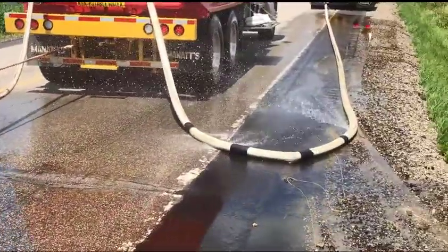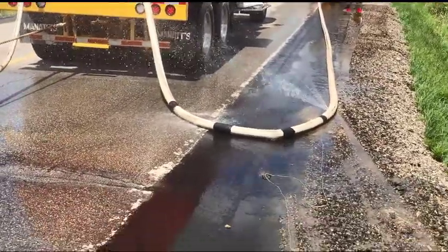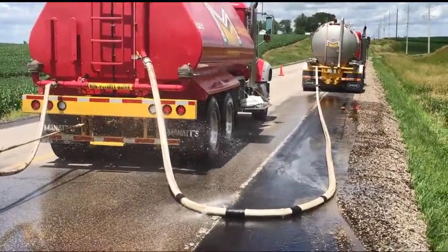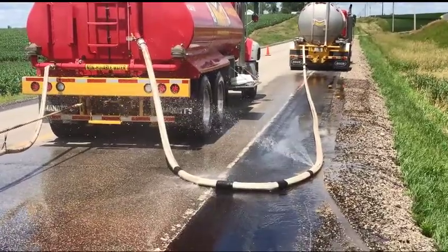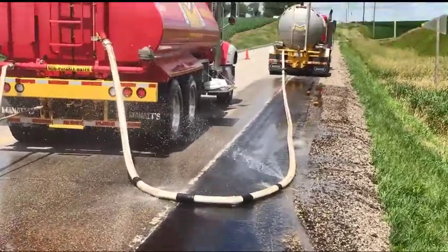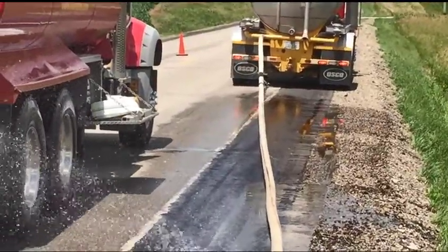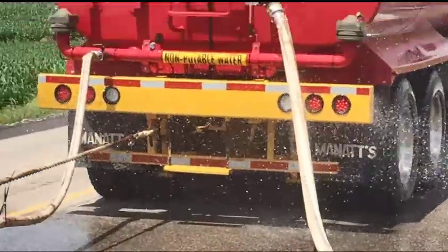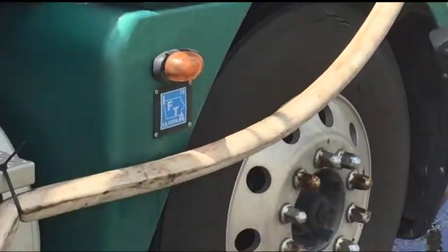But if this had been a gravel or pre-pulverized job, then we would be putting all of this moisture back into that road bed. So that kind of messes up our moisture contents that we've been so critical about and trying to gain. Our compaction is lost because we're oversaturating, and it just makes it very difficult to monitor and control that optimum moisture content.